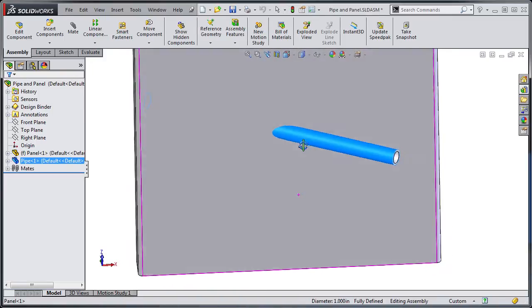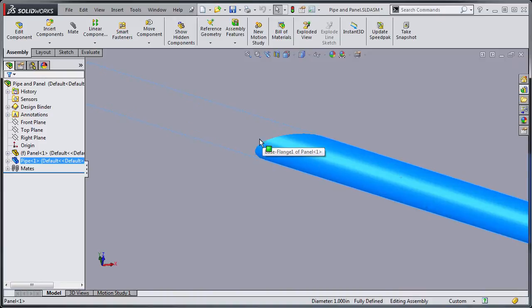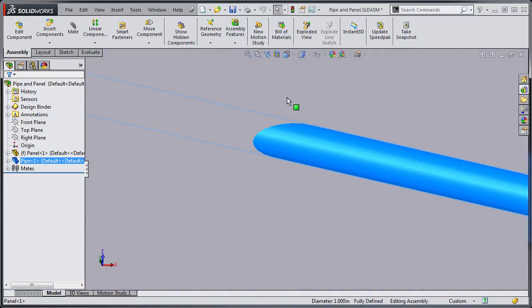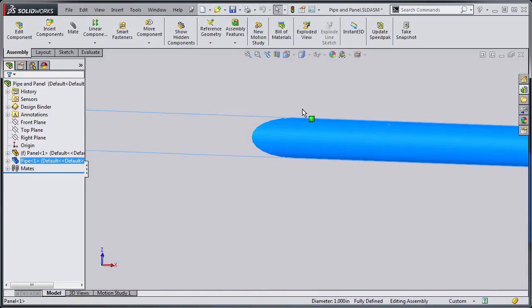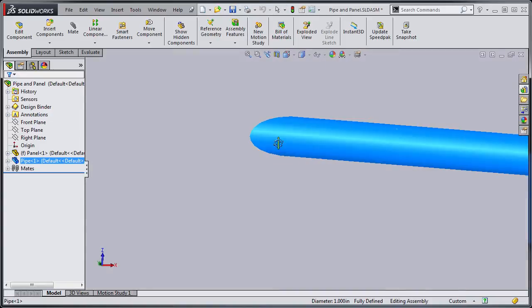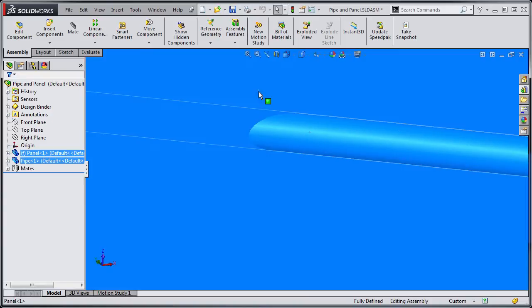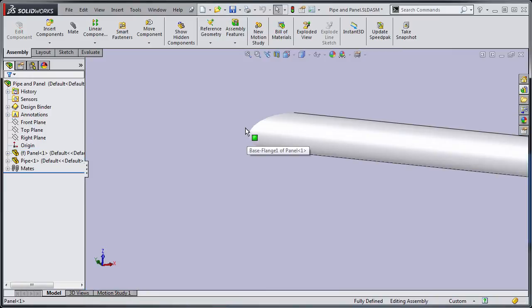An amateur way to do it would be to create an oversized circle. That'll be all nice and good for the width, but for the height I'm going to end up with oversized gaps. Another way of doing it, which might be kind of easy to machine, would be to create a slot. However, if you look at the shape where these two faces intersect, you would find that there would be an elliptical shape.